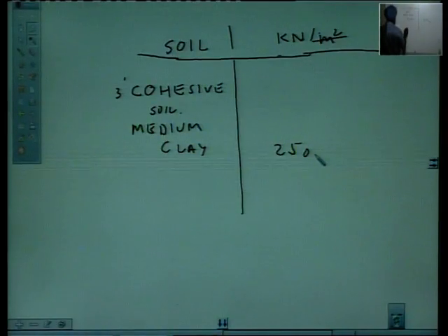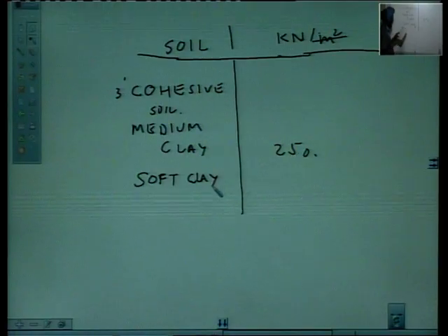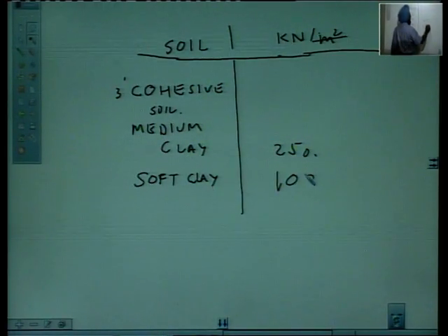Soft clay: one thing I want to tell my students, that clay is very dangerous. When it is wet, then it is very bad, settlement is there, differential settlement is very fatal for a building. So, clay should be avoided.